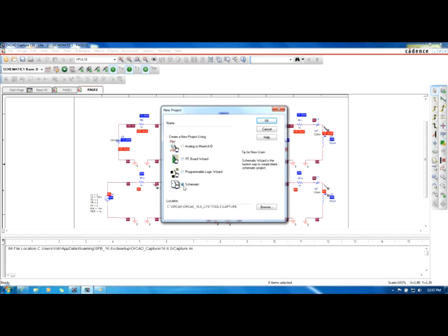A schematic, that's like if I just opened up PSPICE by itself. Right now I'm under Capture. That's going to include PSPICE stuff because this is a SPICE program right here. So analog or mixed AD is telling you that you can do a simulation here. This is what allows the simulator to work.